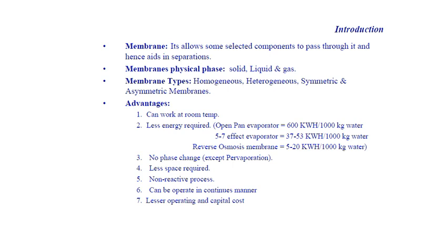So if we compare membrane based separation technology to the other conventional separation technologies, membrane based separation technologies have several advantages. A few are written here. The first important advantage is that membrane based technologies generally work at room temperature. If you compare them to other technologies like distillation, crystallization or evaporation, membrane based technologies like reverse osmosis work at room temperature. If you use evaporation for water purification, then you need a large amount of energy to change the phase, and it will work at a very high temperature.